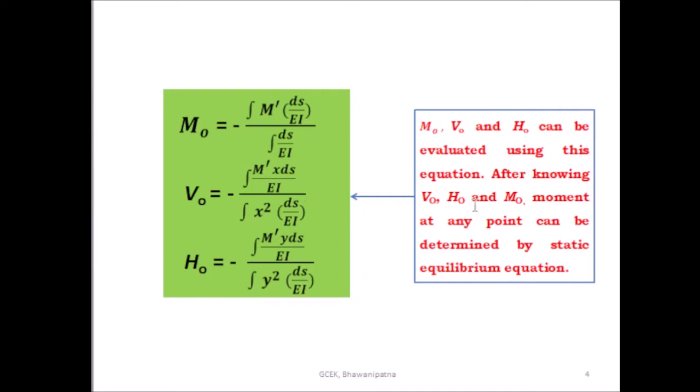After knowing VO, HO and MO, the moment at any point can be determined by static equilibrium equations. So after getting MO, VO, HO, then the moment at any other point can be determined by the static equilibrium equations.